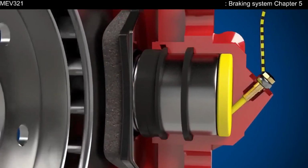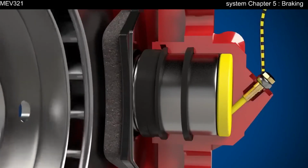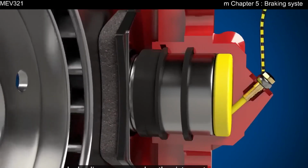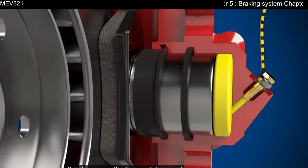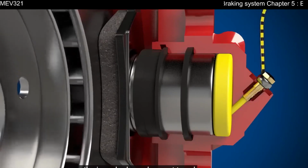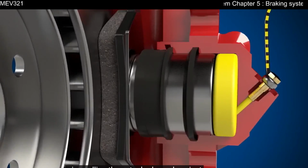The brake pedal is pressed and pressurized hydraulic fluid enters the caliper body. Hydraulic pressure pushes the piston out, first forcing the inner brake pad against the inside of the brake disc. As this happens, the inner piston seal deforms. Now, the inner brake pad cannot travel any further, so hydraulic pressure forces the caliper body back along the slider pins, pulling the outer brake pad against the outside of the brake disc.